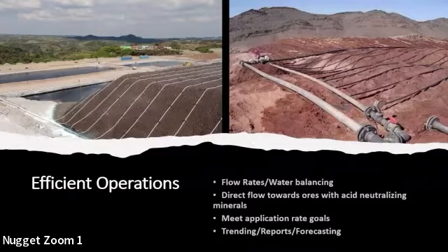Taking the experience from this DCPT evaluation, which reached a depth of some 10 to 15 meters, we were retained to perform deeper analysis on a heap leach facility in northern Chile, which at that moment was over 210 feet in height, and to evaluate the geotechnical properties of the heap and also the ROM facility placed on it.